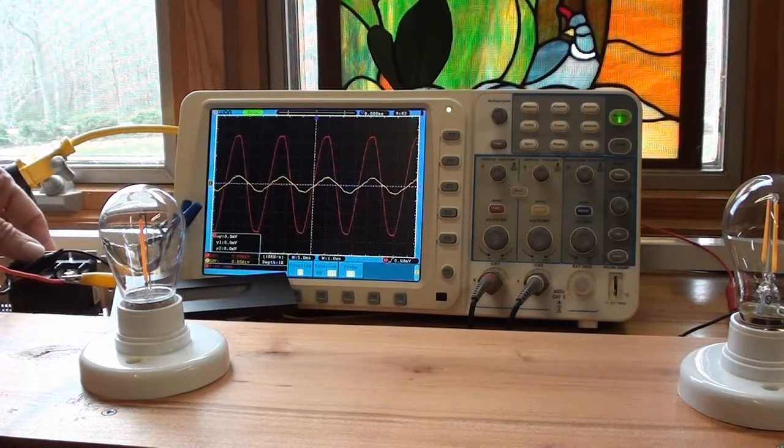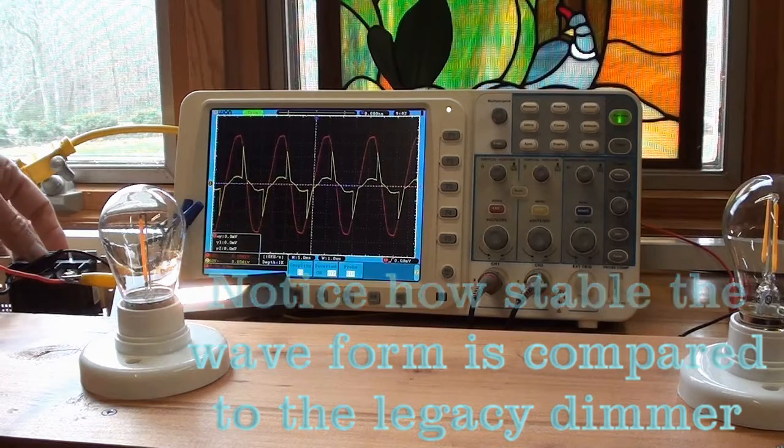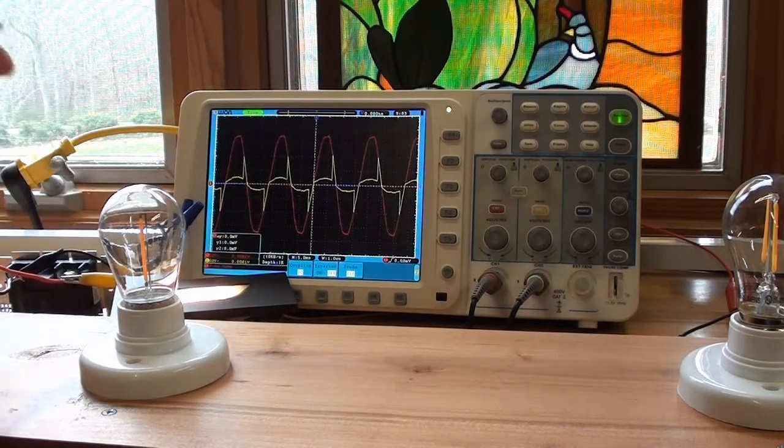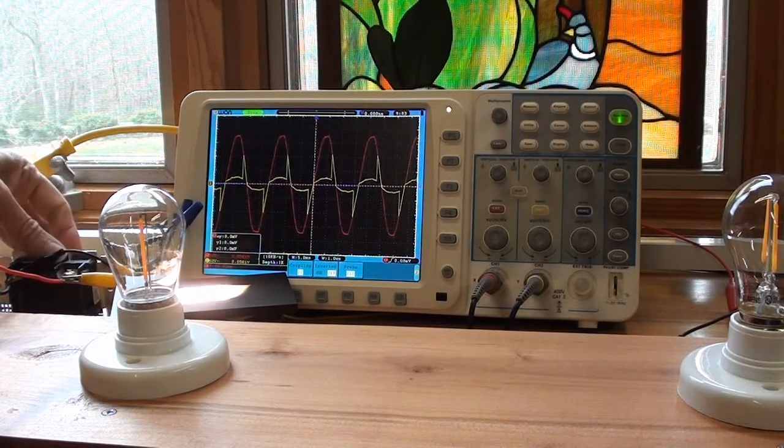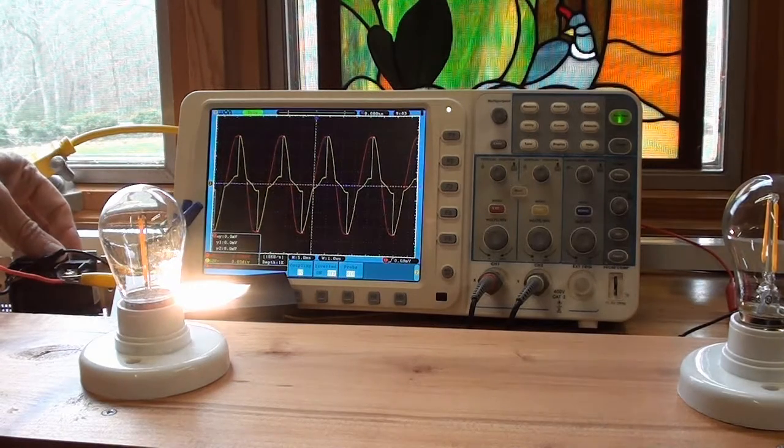Alright, let's try it with the Lutron fixture. Oh, at low level, it's sort of unstable. It's flickering quite a bit. At minimum brightness, it flickers about the same, and it's actually more wavy and more out of control than it was with the legacy fixture, legacy dimmer. Bring it up to about halfway or so, it stabilizes, so virtually the same performance.